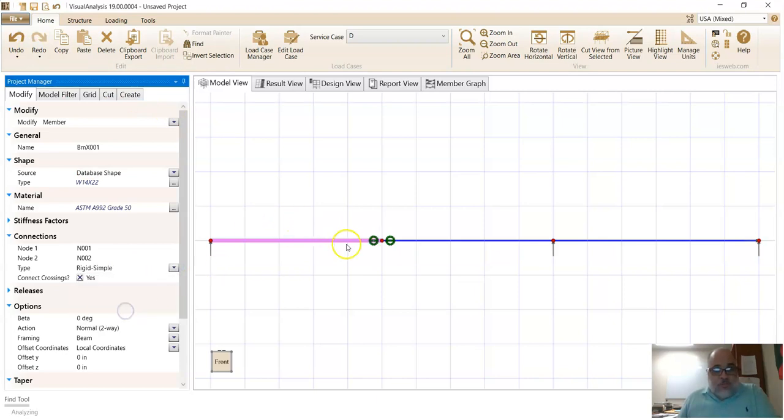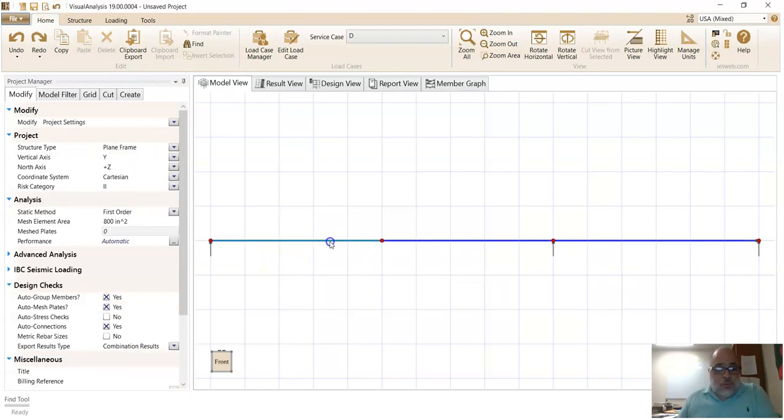It's like putting two hinges and then the structure will collapse. You only need to put one hinge, only one hinge. So I'm going to undo. Okay, so with any of those two solutions, you only need to change one side of one of the members to simple.